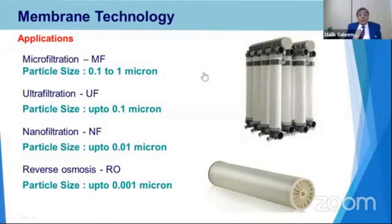I just wanted to clear your concept that microfiltration, ultrafiltration, nanofiltration, and RO membranes have different pore sizes, and based on those pore sizes, we select what we want to separate. If we want to separate suspended solids, we will go for the ultrafiltration membrane or the microfiltration membranes, because we know that the microfiltration and ultrafiltration membranes will remove suspended solids, as they are visible to the naked eye.